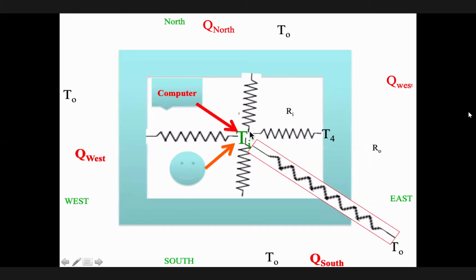It means h times the area of the east wall, T4 minus TI, plus h times the area of the north wall times, I don't know what number it is in your case, minus TI, plus convective heat transfer from the west wall, h times the area of this wall, times T8, 9, I do not know, plus the south wall, and you have two more, one from the floor, one from the ceiling. Therefore, you have 6 surfaces, you have 6 convective heat transfer terms to that one. Therefore, this temperature minus this temperature, minus this, and so on.